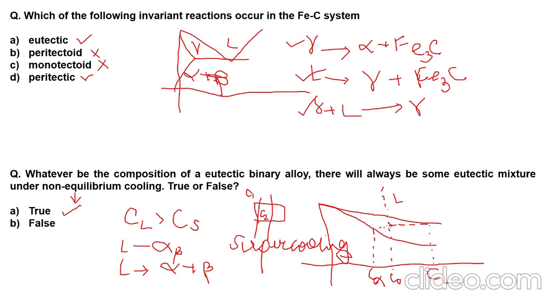But say, for example, when you're talking about blast furnaces or slags in pyrometallurgical processes, you have three components: calcium, silicon, iron. So that is a ternary diagram. The three components interact with one another to form certain phases. But when you have a binary, you have only two components interacting, copper and nickel, for example. You don't have any third component, and you can form eutectic points.